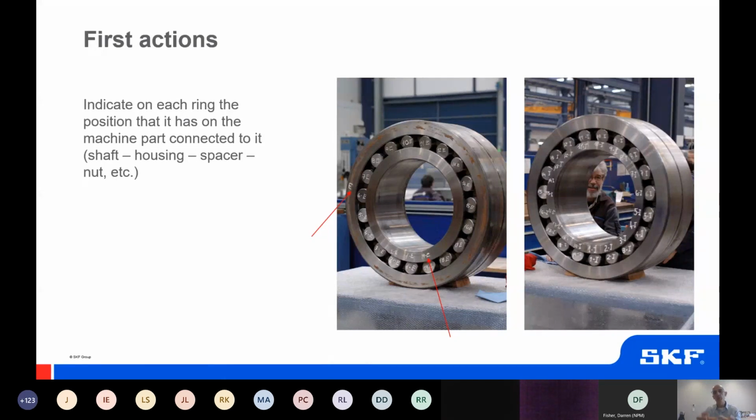And you can say, why would I identify the rolling elements like in the picture? That could be interesting depending on what is found in the bearing, that you know each roller was in each position on the cage. Of course, the rollers are going to be moving around when the bearing is running, but each roller, not because it is designed like that, belongs to a certain position on the cage. And then you can look for patterns between the roller and the cage in each position.